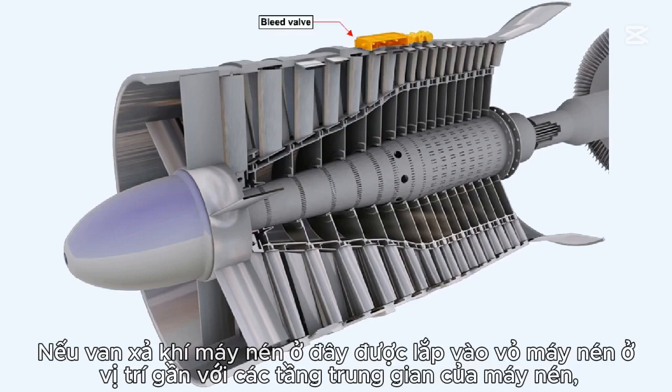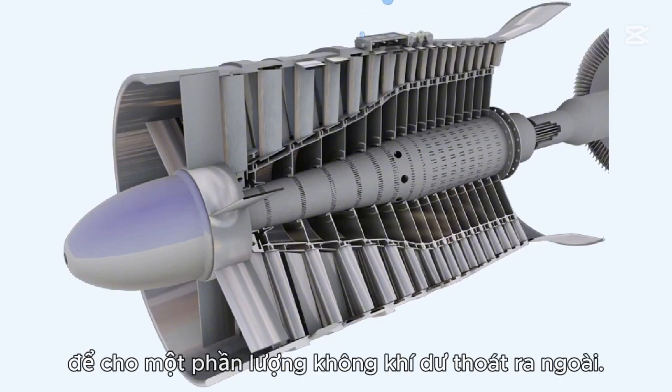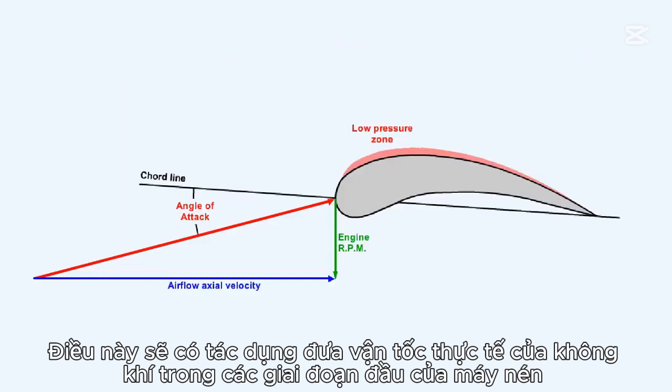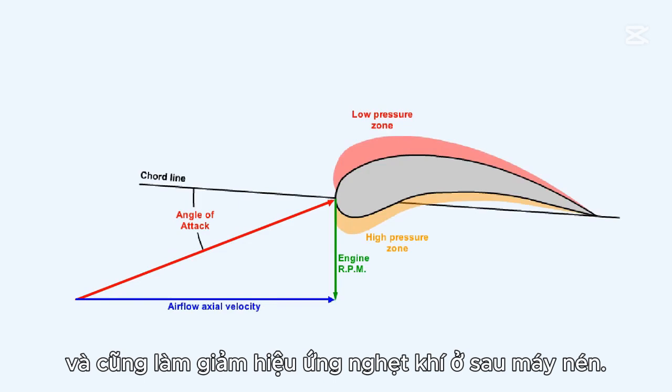If a compressor bleed valve, like the one shown here, is fitted to the compressor casing adjacent to the intermediate stages of the compressor, it can be opened at low RPM and during engine acceleration to allow some of the excess volume of air to escape. This will have the effect of bringing the axial velocity of the air in the earlier stages of the compressor closer to the optimum value, and also of reducing the choking effect in the rear of the compressor.